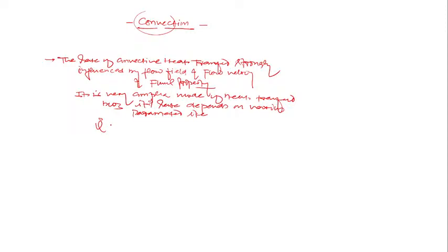The rate of heat transfer will depend upon parameters like delta T, the temperature difference, and area. You know Q = h A delta T. Along with this, the density, velocity, specific heat. So all these weightages you said here, U, rho, nu, Cp, K, are all fluid properties, yes or no, along with Lc also.